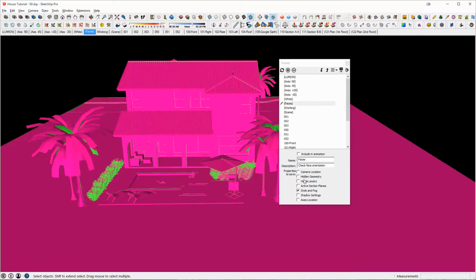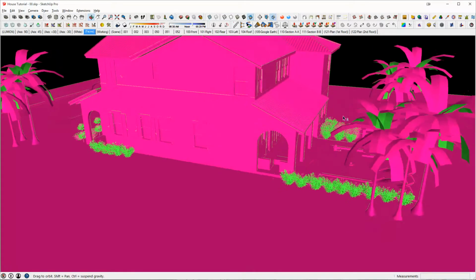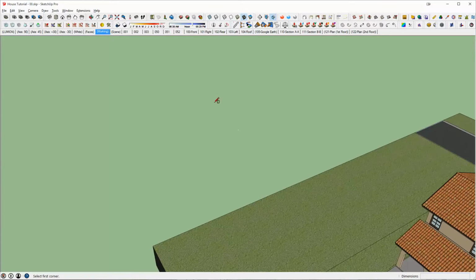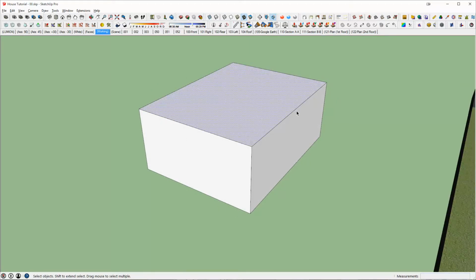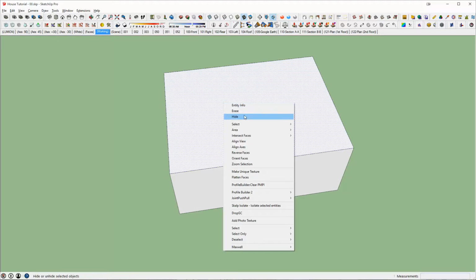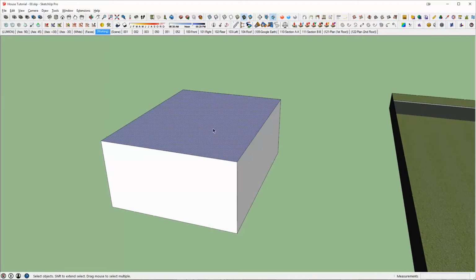My faces tab is something similar, but this only has a style attached, and what this style does is it looks for front and back geometry, and I could probably show you a little better right here. So if we have this cube, and we've talked before how the white face is the one that should always be facing up no matter what you're looking at. And my faces tab really helps resolve issues if there's not. So this reverse faces is putting the blue face up, and that's not what I want.